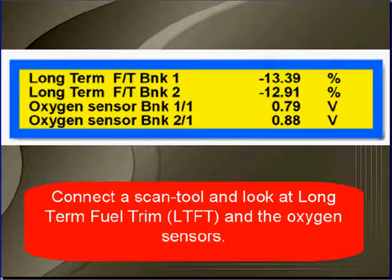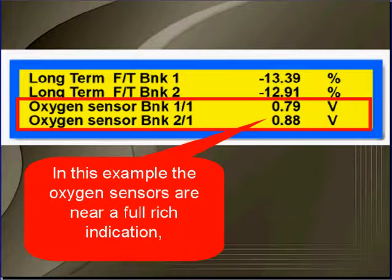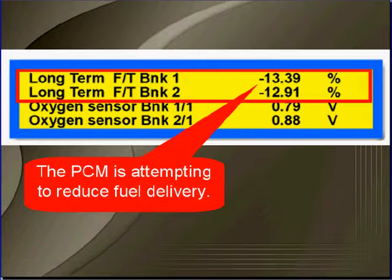Connect a scan tool and look at long-term fuel trim and compare it to the oxygen sensors. Remember, you have to make sure that the oxygen sensors are good before using them to diagnose a problem. Bad oxygen sensors are a common cause of this failure. In this example, the oxygen sensors are near full rich. The PCM is attempting to reduce fuel delivery.